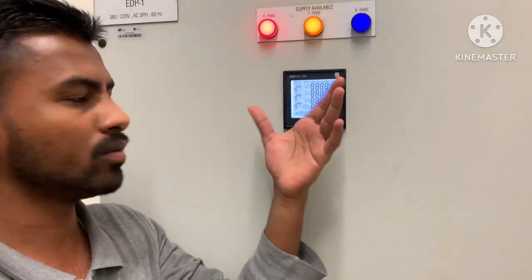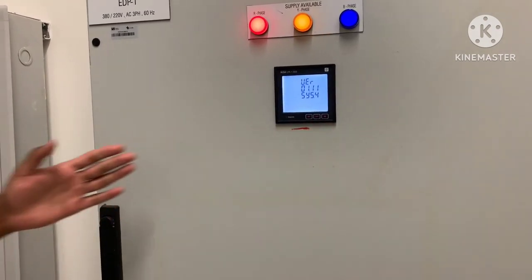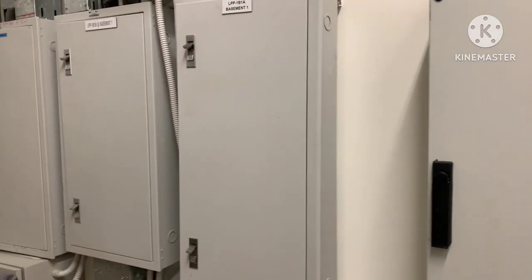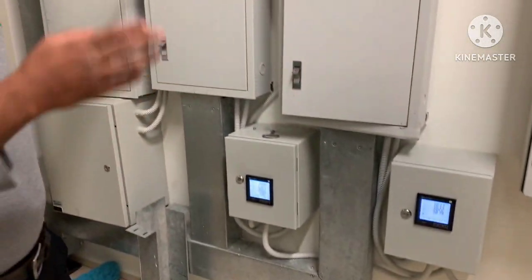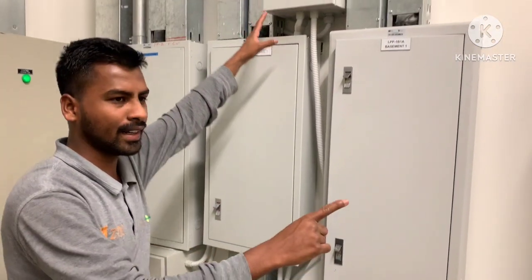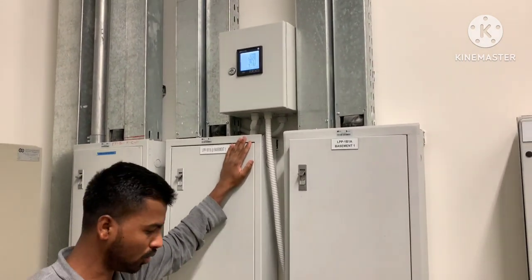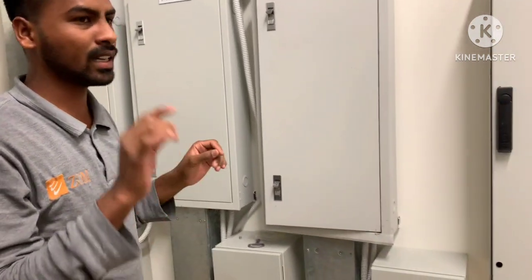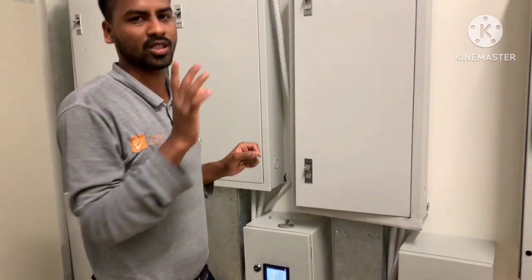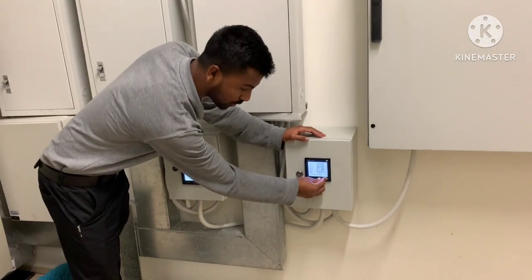I've already shown you the address for this meter. Okay, I will show you another meter over here. As you can see, 2 meters are on the downside and 1 meter is on the upside. So as you can see, the baud rate for all the meters must be 57.6 kilo. Okay, if the baud rate is different, it will no longer communicate. But the address for each meter must be different, must be unique. For this device, I will show you what the address is.